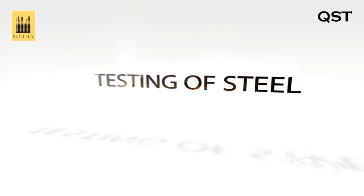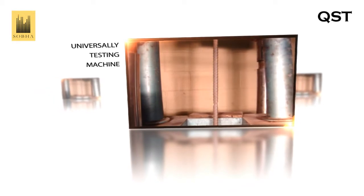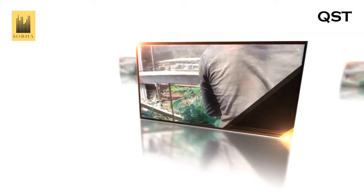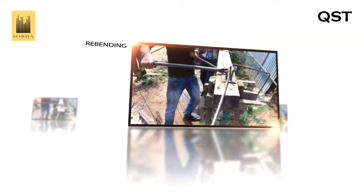Testing of steel. The steel that arrives at the site should be visibly checked for any discrepancies. Deformed, severely corroded, cracked and split bars should be rejected. Samples should be taken for lab tests such as rolling margin test, tensile strength test using universal testing machine. Then bending test. Next rebending test.